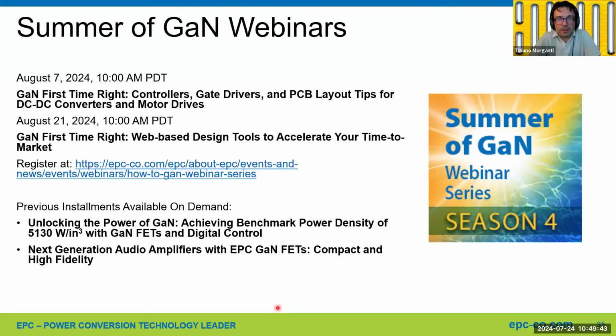So the next step for us is to try to remove Schottky diodes, keep the dead time long for low power operation to optimize the idle losses, and reduce the dead time when the output current is high enough to optimize the losses at high power by reducing the freewheeling losses just by reducing the dead time. So we don't need any other switching device than our EPC FET. So that's already a good switching device. We don't want to compromise with adding other devices in parallel.